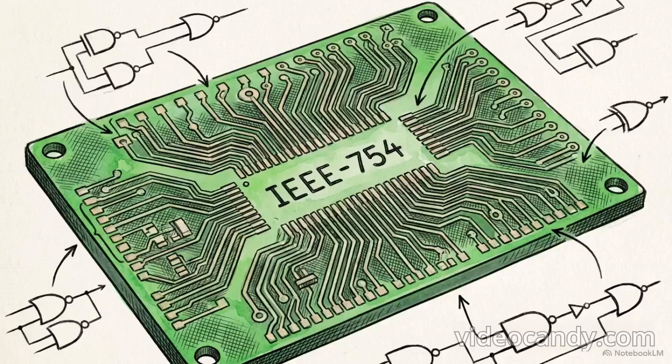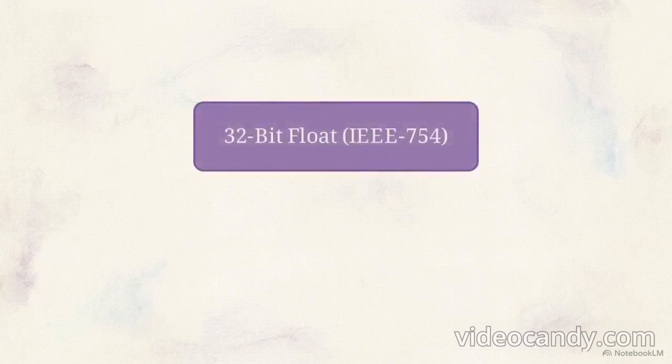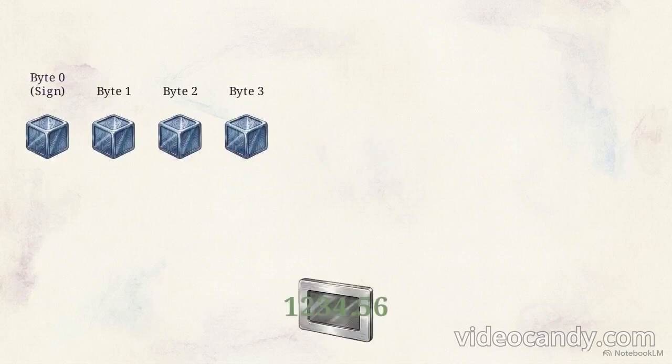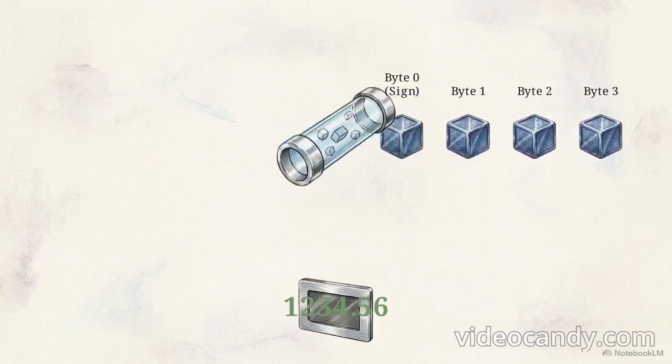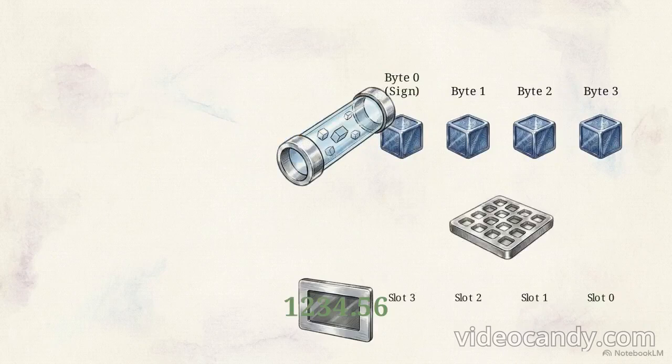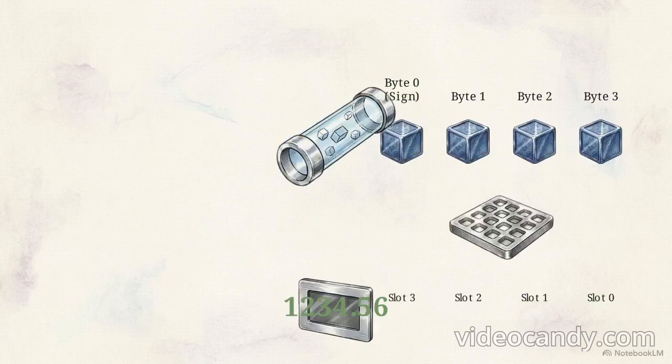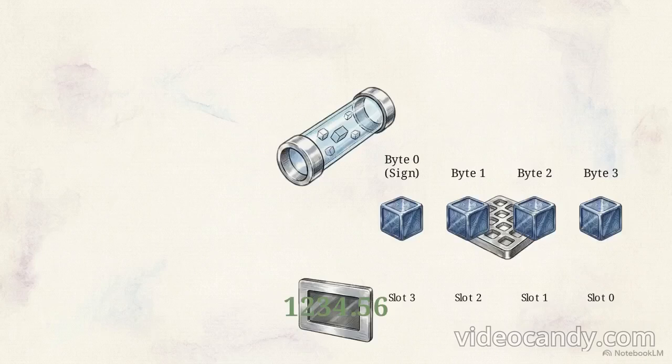Problems still occur even when the register addresses align perfectly and the analog data remains unreadable. Most industrial control systems rely on the IEEE 754 standard as the architecture for processing 32-bit floating point numbers. To transmit a 32-bit float over a network, it must be broken down into 4 distinct 8-bit bytes. The receiving PLC must read those bytes in a specific sequence, known as endianness. When a slave device packages a floating point number for transfer, it transmits the sign byte first, followed by the rest. However, master systems expect to receive that sign byte in the highest of the 4 addresses, not the lowest.